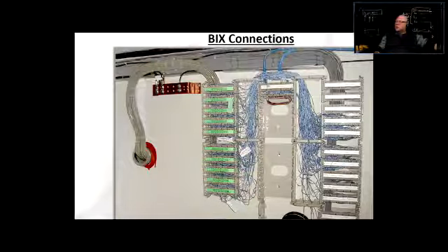So you would tap into that pair from one side using cross-connect wire. And in this case here, it just goes on top and is terminated somewhere else. It looks complicated, but if all things are labeled and you know how it works, then it's just a lot of the same thing, right? So it's not as intimidating as it looks.